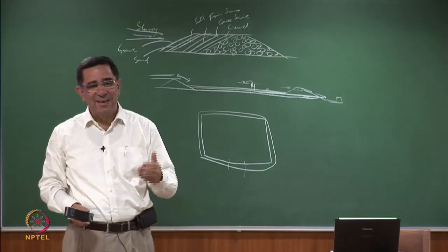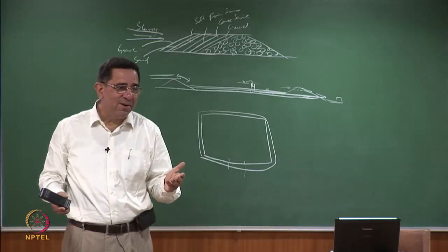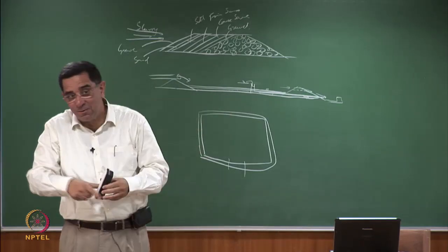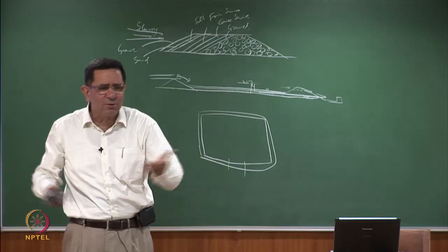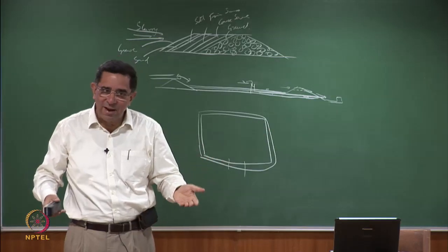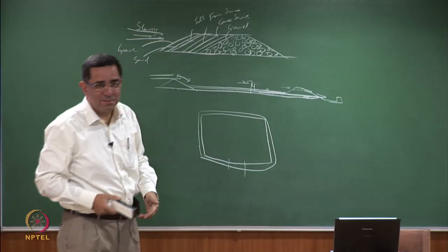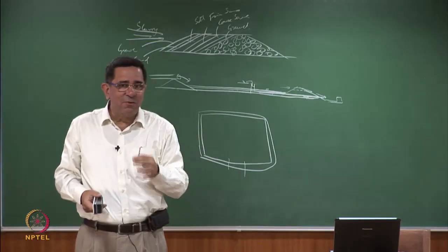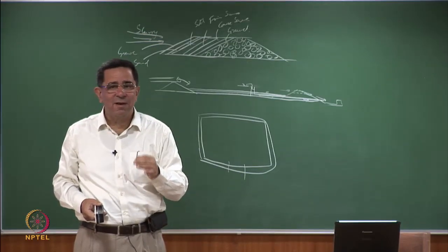Absolutely. Once your fines start to settle, it will start to clog up your drain. You must have the capacity that what is inflowing must flow out, otherwise the water level will rise. So suppose it chokes it, you will say, so what? At least the fines are not going out. Then your water level is rising, and finally what will happen? Water will start flowing over from the top, and again the fines will come out. So flexible filters have not really worked.